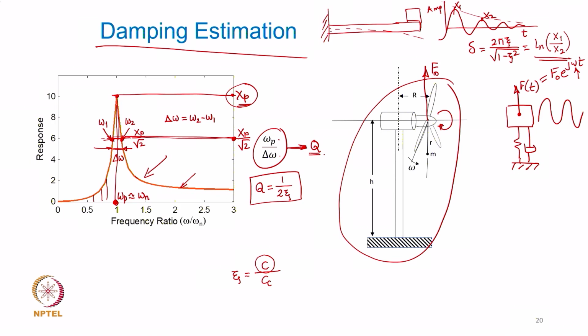By putting some kind of a sensor or accelerometer to measure the vibratory response of this system, once I get this response measured using sensors, I can track the amplitude decay, and then from that amplitude decay I can get x1 and x2, which means I get this ratio quantified, and because it is the same as the logarithmic decrement,